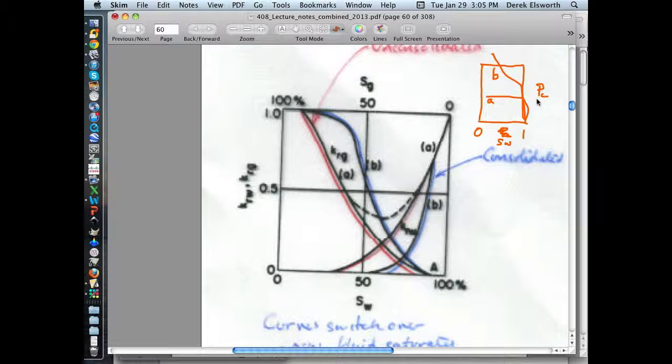Give it a go. Yeah, you can do it. Does A have a uniform pore size? Yeah, fantastic. So you know that once you invade the pore size, you invade the whole thing, so A is uniform. B is less uniform, so that's the one thing between those. What else? So you can say something from the shape of that, that's great. What else can you say from the magnitude of this intercept? Is the biggest pore size in porous medium B larger or smaller than the one in A? Pore sizes are smaller. Yeah, that's right. You don't put your hand up, just shout. It's fine. Great, fine. So those are two things.